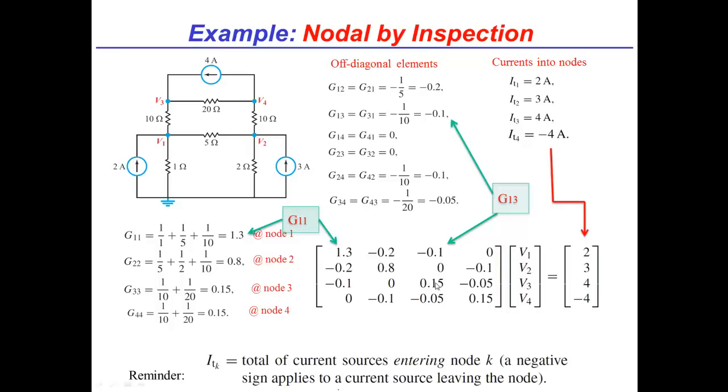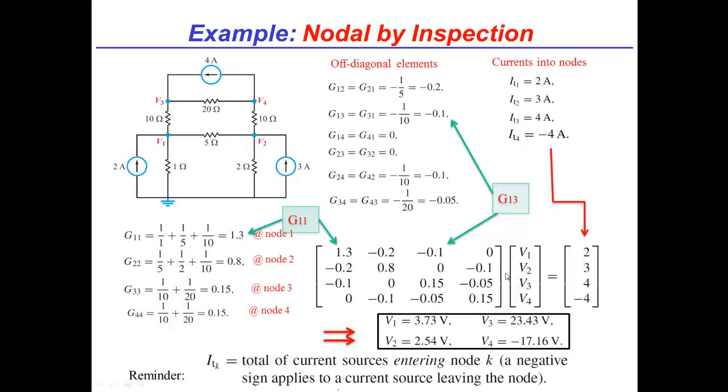The advantage of this is you didn't actually have to go and write the KCLs, etc. That's right. Having said that, there are few occasions where you would want to do this by hand. There's a certain pleasure in doing KCLs for yourself. I suppose. And so, this is mainly to show you the underlying matrix that develops and how this applies. It would basically be solved within a computer. And what you finally get is you can then solve the equations and you get the answers for the voltages. So we've calculated the node voltages without ever actually doing a KCL or a KVL.